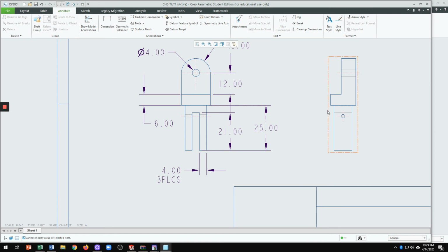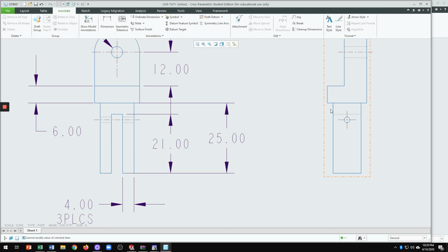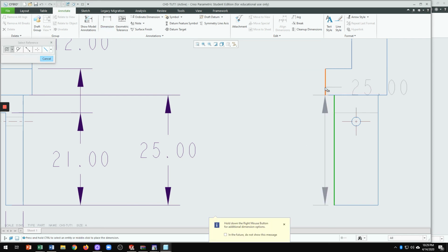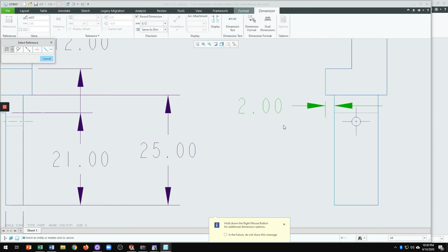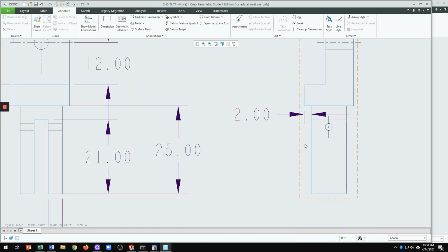Then there is one more dimension in here. Remember that edge that we gave a plane, that 2 unit and into the face opposite of this face, just going in. So that's 2 units. I can use the manual dimensioning, for example, if you want. Just click on this line, then hold the control and click on this line here. You can see that that's 2 units, with a middle click to position it. Okay, so let me cancel that. So I just used manual dimensioning to do that.